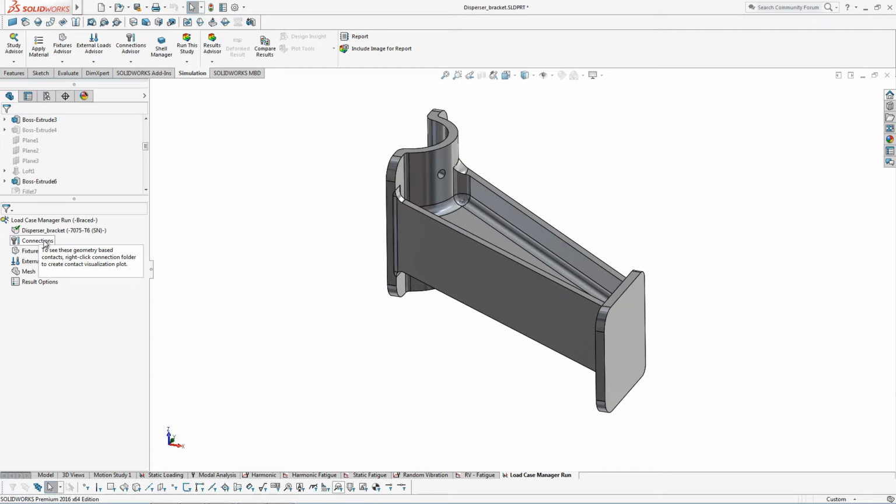So for instance, this model, I'm going to make the assumption there's going to be a downward loading, same load value, but an upward type loading, a lateral loading, a torque loading, and then there are going to be some G loading, so a 20G vertical and a 20G side load. And then there are going to be some secondary load cases where we're going to combine some of those initial load cases very, very quickly.